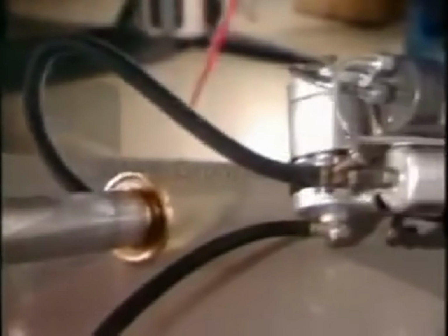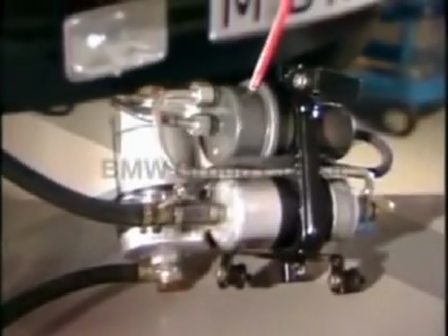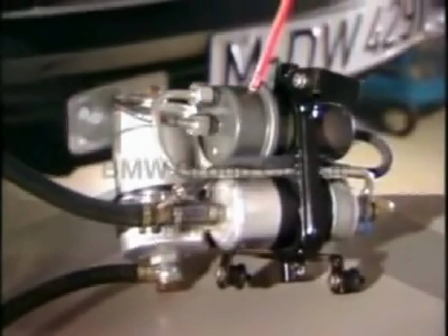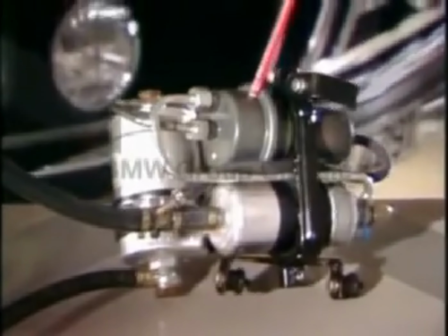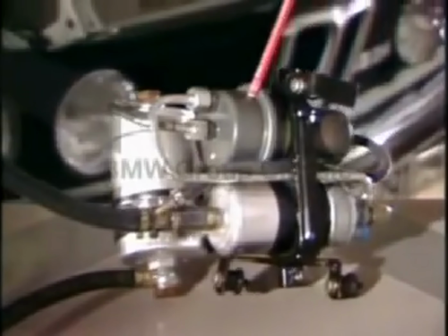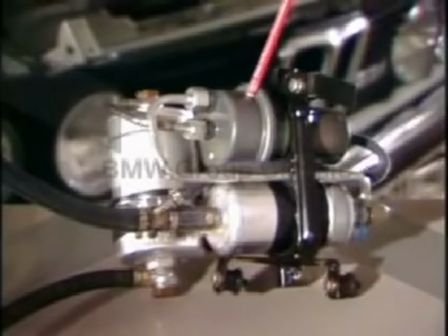The fuel pump draws the fuel from the tank through the fuel pipe and pumps it into the pressure accumulator. This pressure accumulator mutes the delivery pump noise and maintains a specific pressure in the system after the ignition has been switched off.